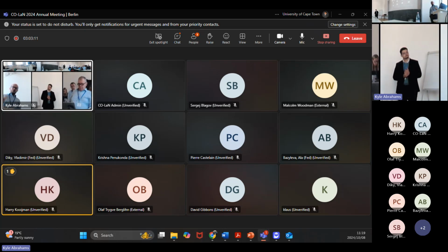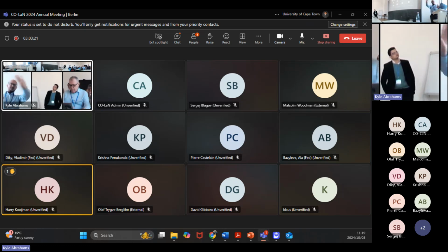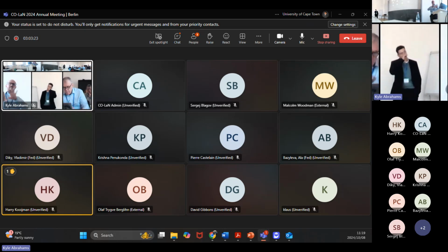From the distribution of the atoms, so carbon, hydrogen, and oxygen, and also the ultimate analysis of your biomass, you know how much cellulose and hemicellulose is present, and that's fine. From that one, you can estimate the distribution of the building blocks identified by Ranzi for the lignin, and then you use this kinetic model using lumped molecules.